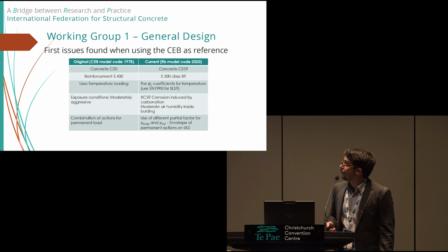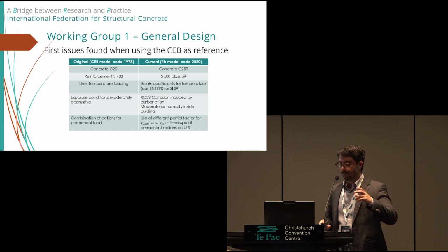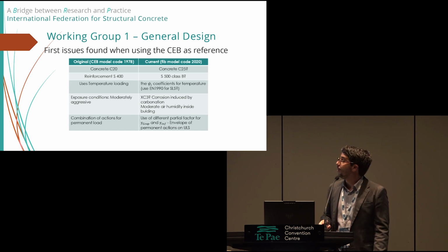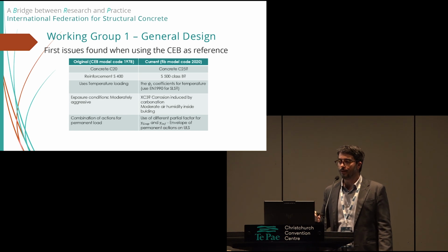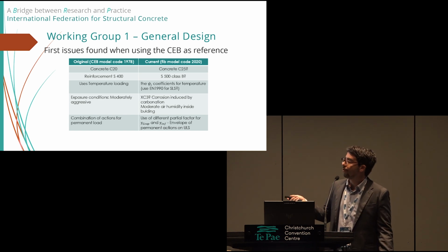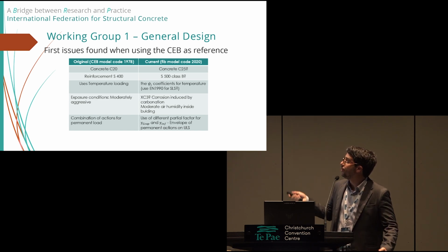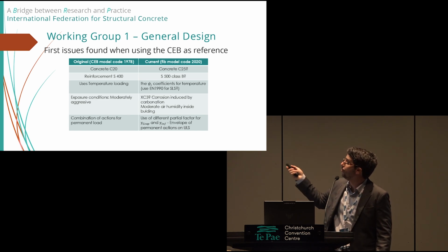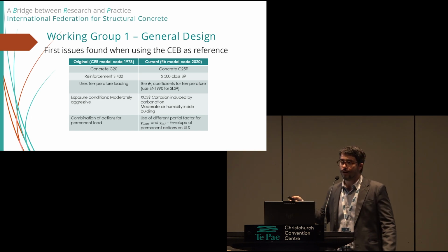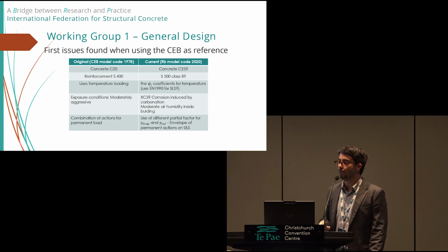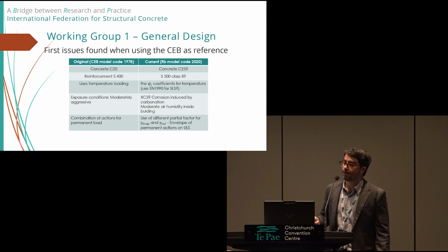Here are some issues that we found when we were looking at the model code examples. They use concrete of 20 megapascals, which is not usually used anymore, so we changed that to 25 or 30, which is more conventional nowadays. Reinforcement as well, they use 400 megapascals. We changed it to what we usually use nowadays.